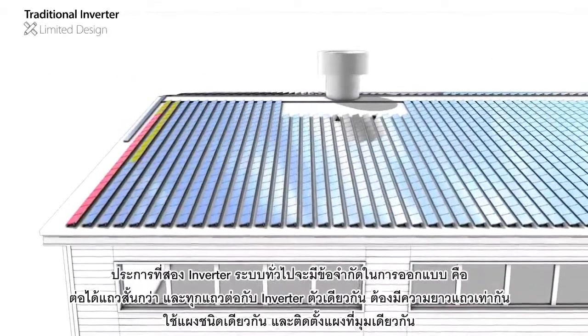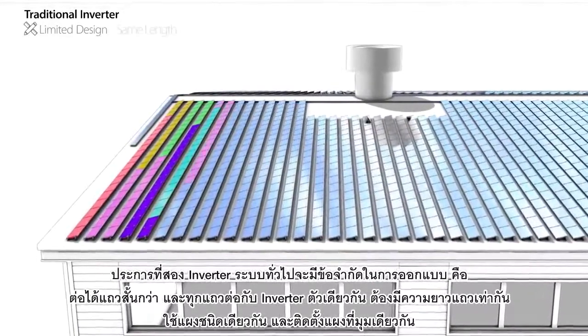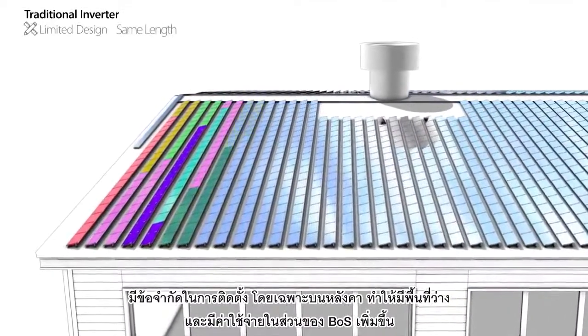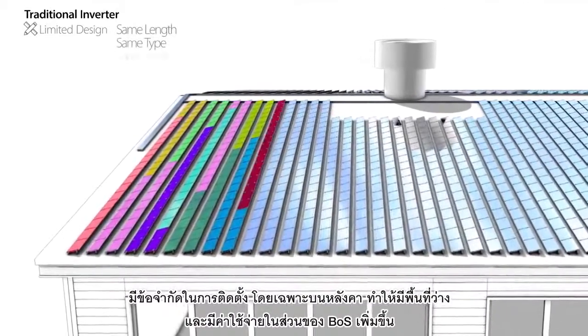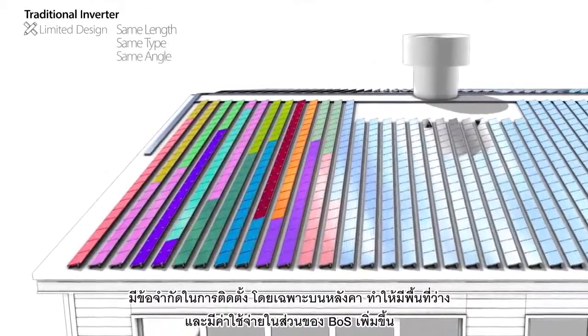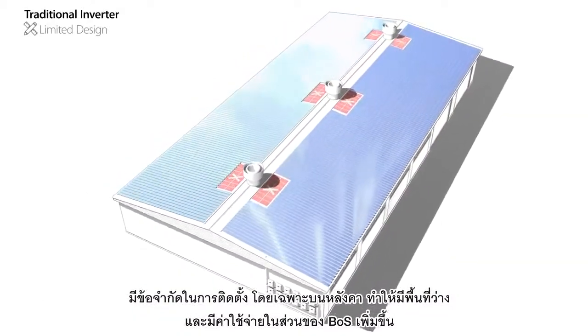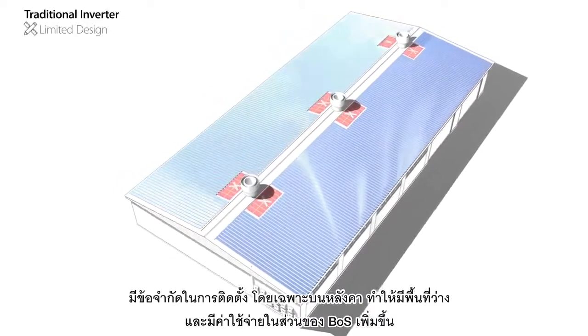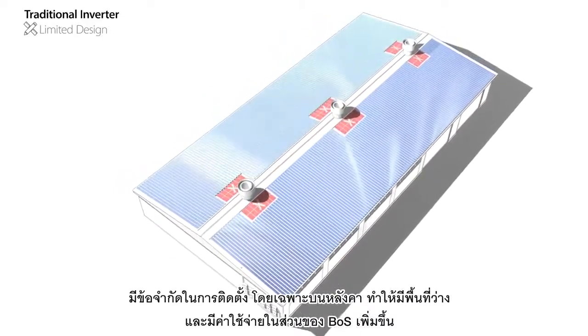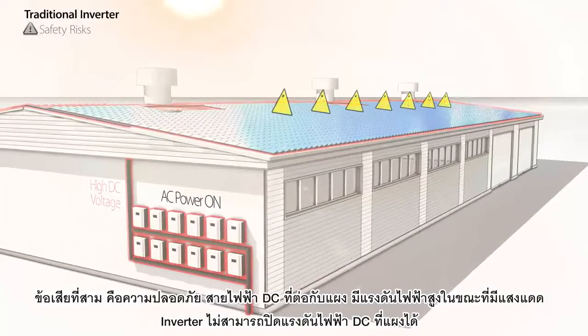Second, the traditional system has design limitations. Strings are shorter, and all strings connected to the same inverter need to be at the same length, use the same type of panels, and be positioned at the same angle. Real-life installation constraints, especially in rooftop systems, result either in wasted roof space or unnecessary duplication of balance of system components. A third drawback is safety issues.